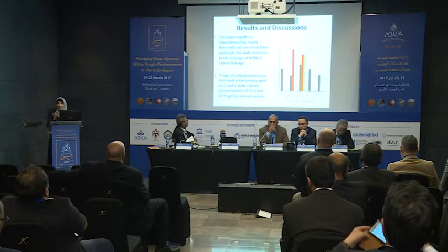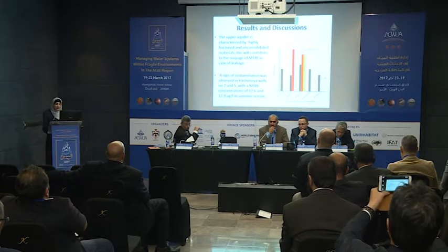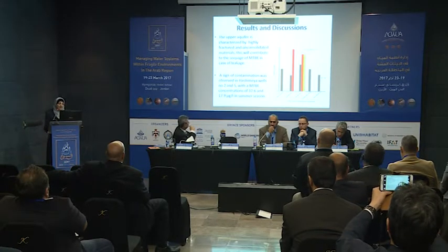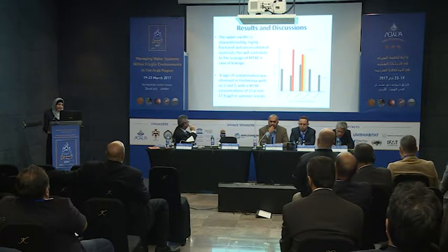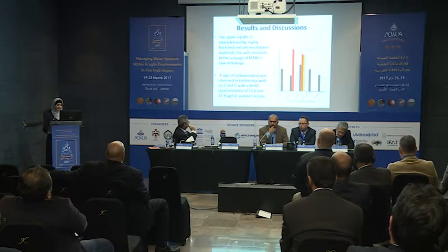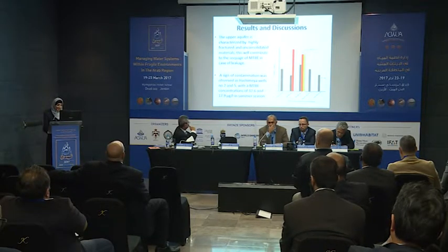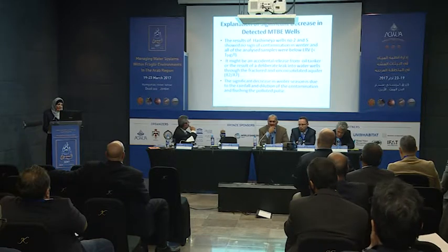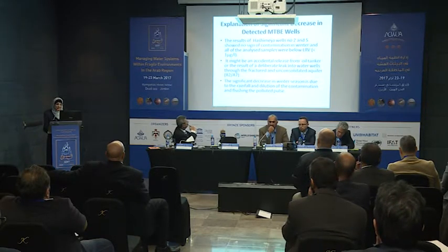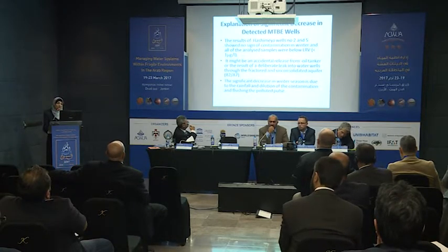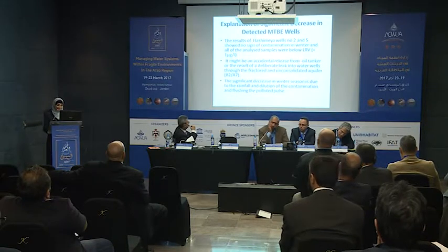Now, according to the main study regarding the detection of MTBE and BTEX, we detected some MTBE in Hashimiyya wells number 2 and 5, but this was only one time in summer season. And this sign of contamination disappeared again in winter season, and the results were below the lowest reportable value, which is below 1 microgram per liter. And how do we explain it?